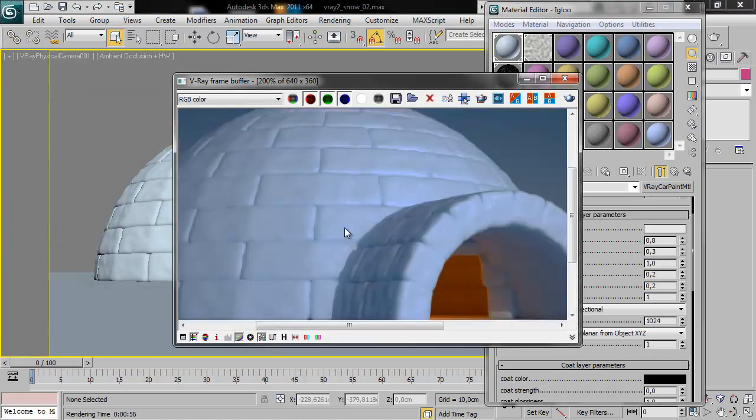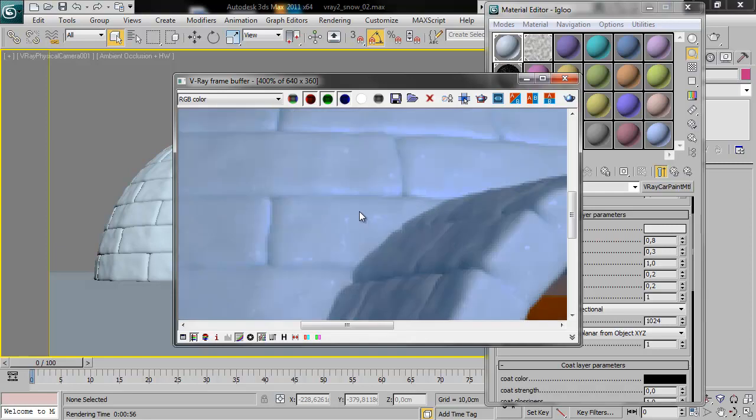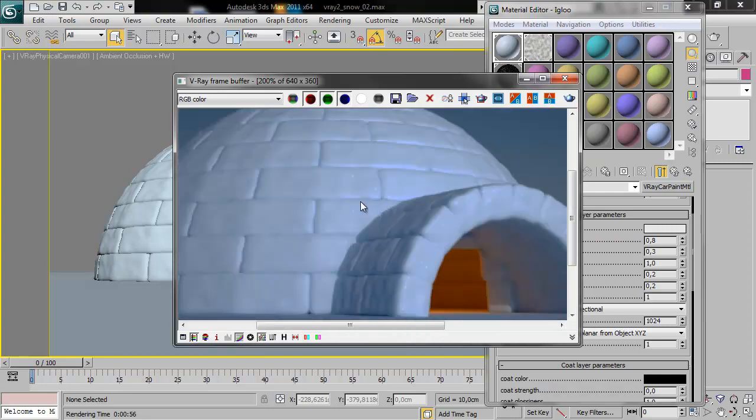And as you can see, the VRay car paint material works really well for adding that small extra sparkle to other kinds of materials, so it's not just restricted to cars. Anywhere you need to use sparkles or flake-like structures, you can put the VRay car paint material in a blend material and add these sort of details. It can be used for snow and ice, and even certain makeup effects on characters if you need that. So this concludes the VRay car paint material section of these videos.